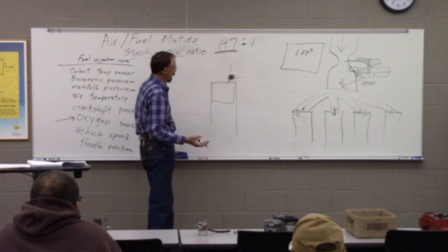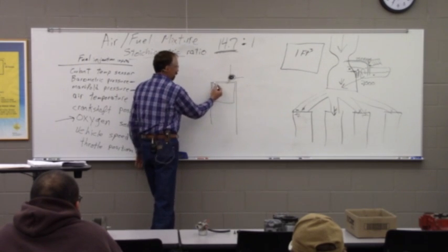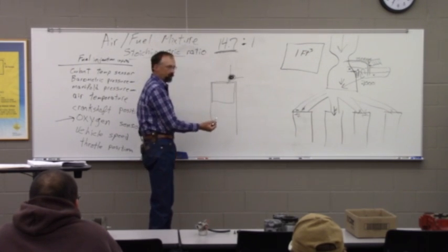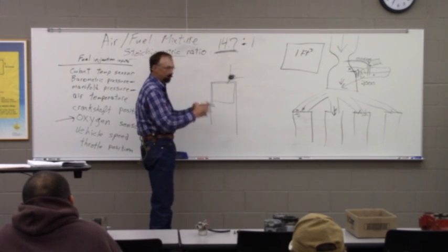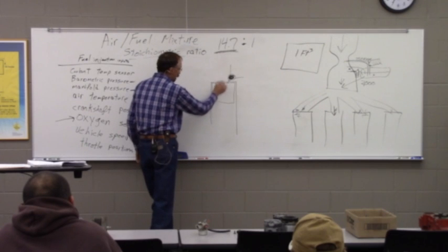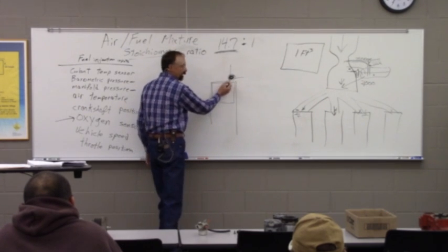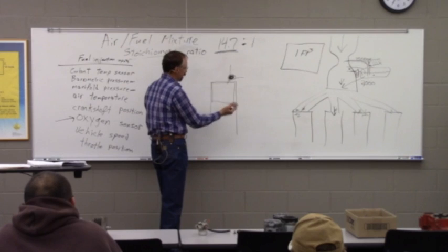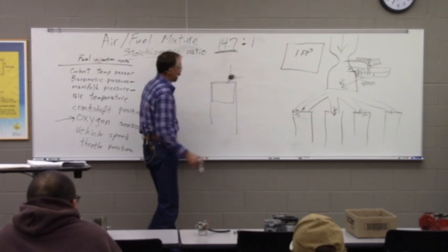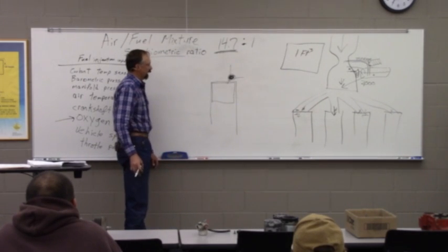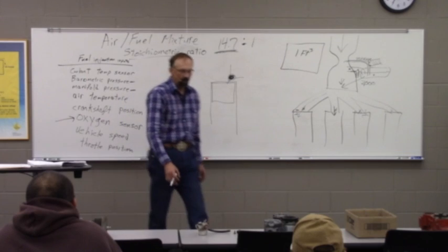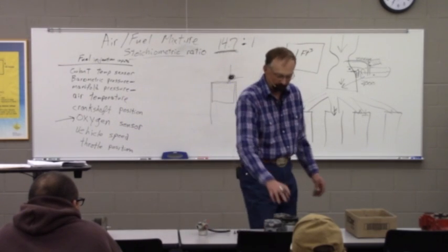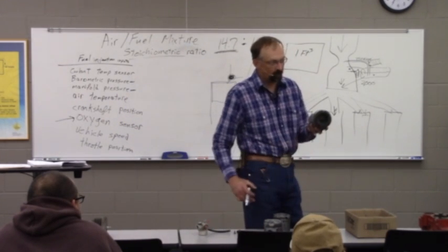At that time, most of those engines were built with flat heads and flat top pistons, and they needed to get this swirling action going to make the combustion start and start that piston traveling down. So they did it with these pre-combustion chambers, they called them. And it worked, but it was found to work much better when they moved that combustion chamber into the piston top.